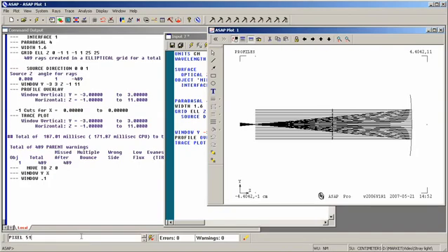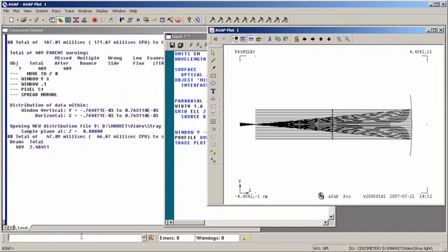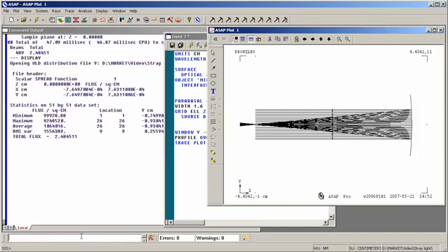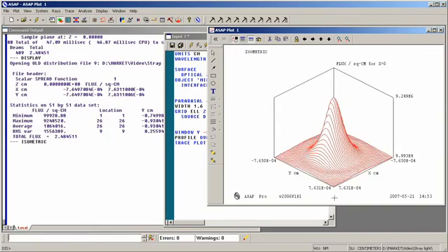Set up a resolution. And instead of doing something like a spot command to show me the geometrical spot diagram, I issue a wave optics command, which is spread normal. Give me this point spread function. ASAP calculates the function, writes it to a file. I use the display command to read the file and an isometric command to actually get a distribution. And here is my wave optics distribution at the focal plane. We see it's not a perfect spot diagram, but rather has the rings that we associate with doing wave optics calculations inside ASAP.